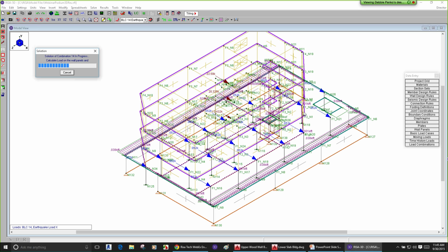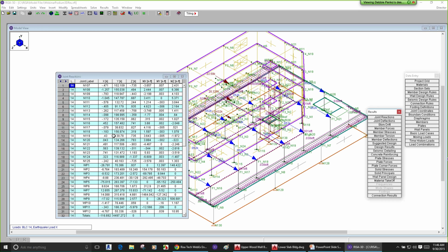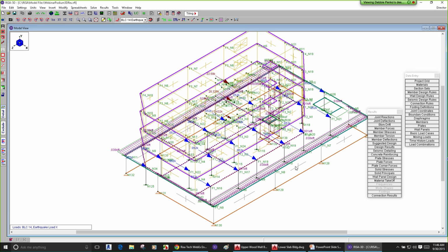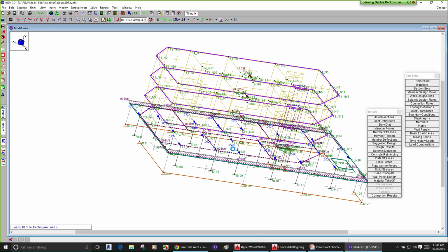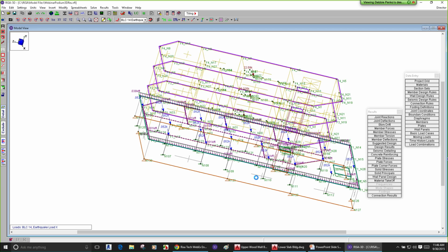You'll see the semi-rigid diaphragm, really helpful for us to see how the loads get distributed. And what you also know is that we are having all those wood walls just sit right on the diaphragm. Because it is a semi-rigid diaphragm, it has some stiffness to it. We can let that just sit directly on top of the lower structure. So we've got a solution present.